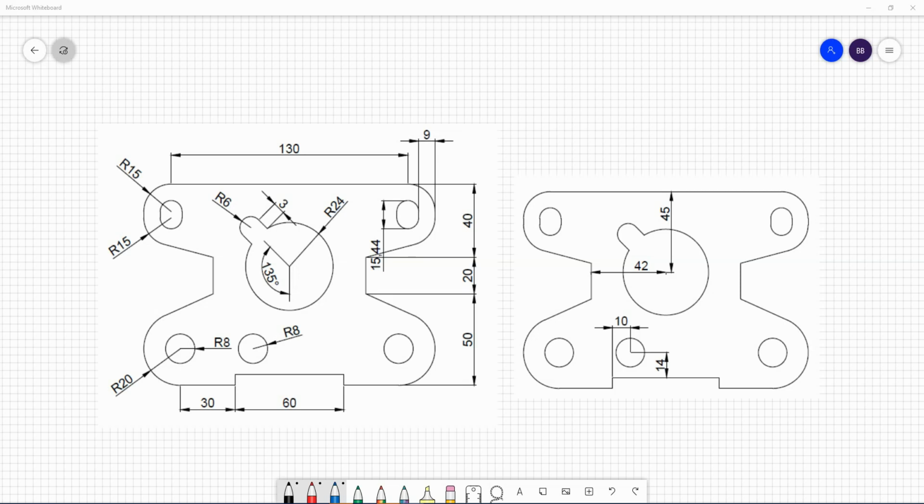So today, this tutorial is going to focus on using features such as the mirror feature, which we're going to draw a section of our shape and then mirror it across a symmetrical line so that we basically decrease our workload, not having to draw every single component. Also, we're going to be using some other features such as the arc tool. We're also going to use the circle tool, both diameter and radius. We use the line tool, the offset command, and we're also going to look at some features such as rotation and also look at doing a couple of dimensions on our layers. So let's break down this drawing and let's get started.